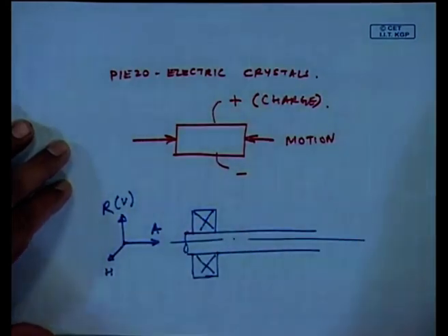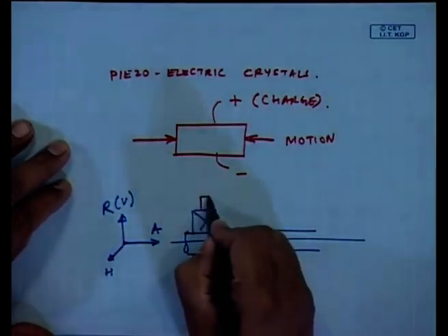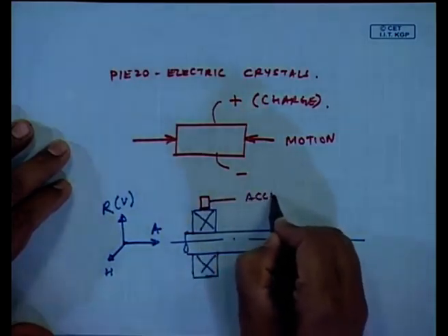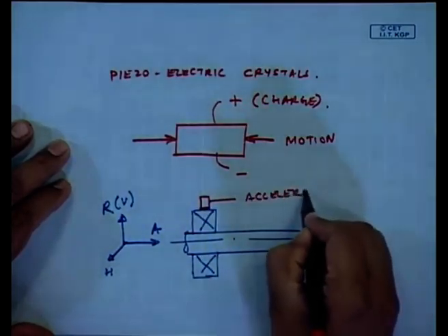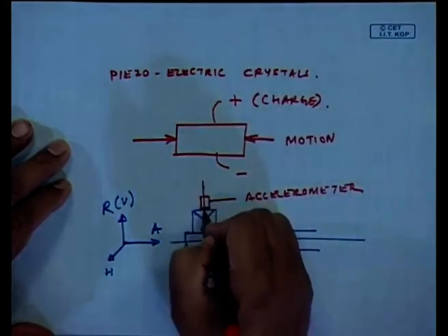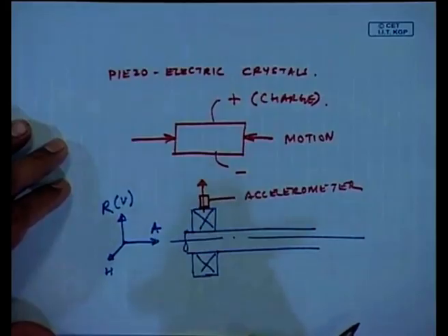So, if I put an accelerometer on the bearing housing here, it is sensing in only the vertical direction.